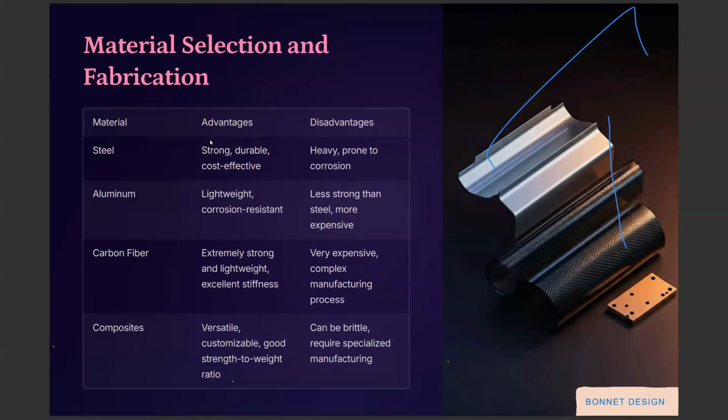These are certain materials that are widely used in the automotive sector, from steel to aluminum, and they also use alloys of aluminum. Carbon fiber is used extensively for race machines, for racing purposes, because it has to be very light. If you have a crash and the part gets damaged, carbon fiber is very light, but at the same time it's not very reusable. That's one limitation. If it breaks, it just breaks, you cannot repair it, you just have to throw it away.